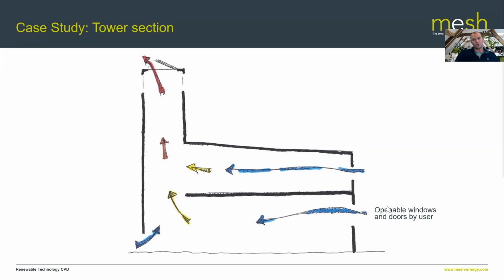So I've just put some quick notes against this one, just to help you here. As well as opening windows and doors, they had trickle vents in this project. I think the air tightness test that they did when they tested the building at the very end was around 5 or 6 by way of an infiltration rate. Design is about 5 for building regs at the moment.